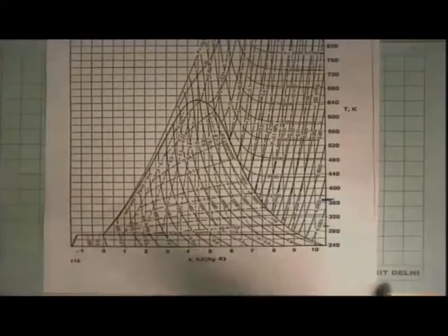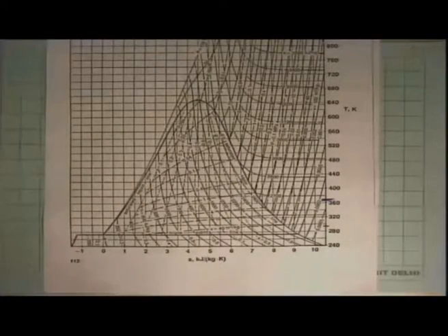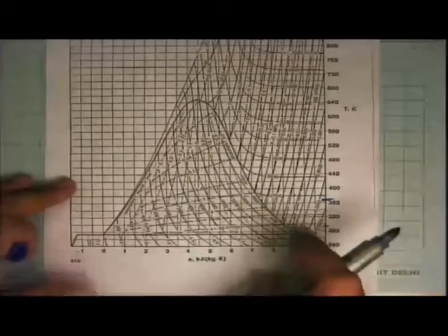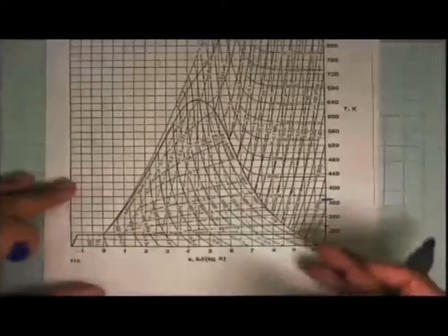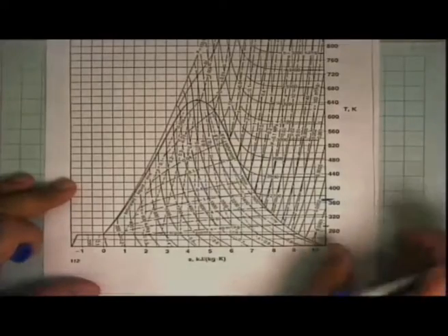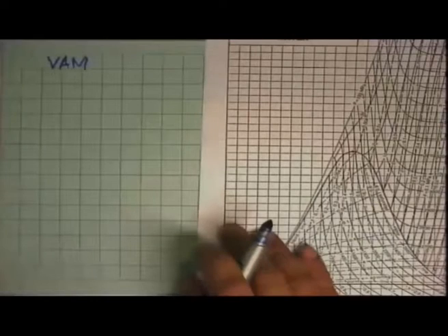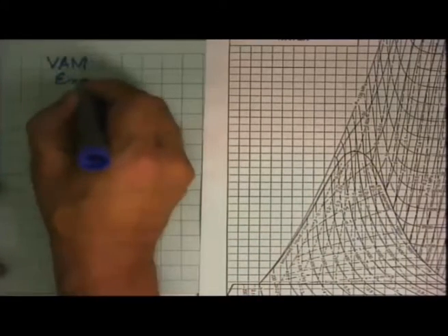And to get any reasonable amount of cooling effect, this whole system will become very huge, very bulky, and so you'll have to make a compromise and say, look, only if I can use all of this in a very compact way, then I will use water as a refrigerant. But otherwise, water as a refrigerant is in fact not possible for freezing at all. I can only use it at best for air conditioning, and that is the central idea of what is called a vapor absorption chiller or a vapor absorption machine, where water is the working substance. You operate at very, very low pressures throughout the cycle, and you have to keep worrying that air does not leak into it. And that is where the engineering becomes complex.